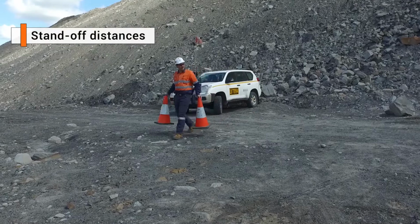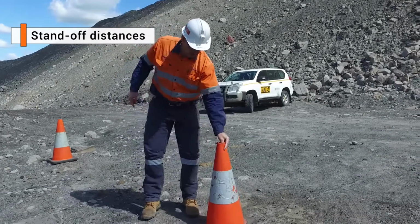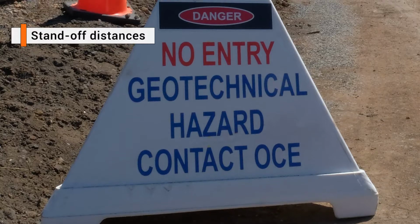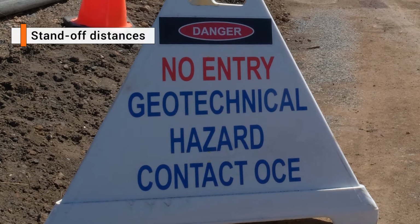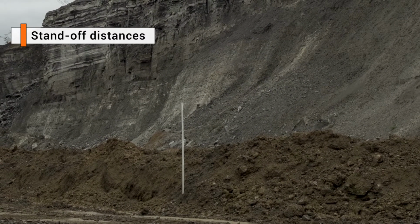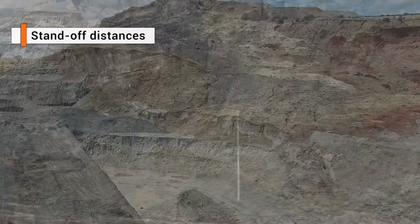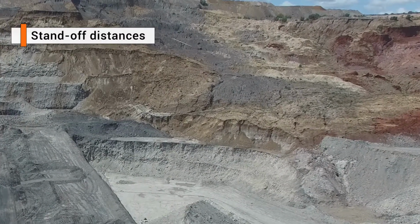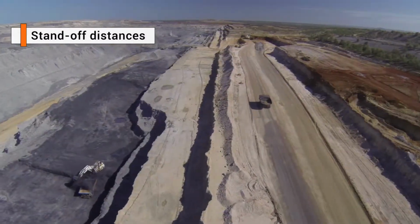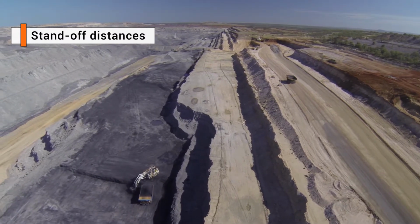Standoff distances can be applied at both the crests and toes of excavated or dumped slopes. Standoff zones are typically based on empirical charts, past performance of slopes with similar conditions, or modelling results from software simulating individual rockfalls or slope failures. The applied standoff distance should be appropriate for the type, size, likelihood and consequence of slope failure. Many sites have standard restriction zones that are applicable at all times. Increases or decreases to these standard restriction zones are then made on a case-by-case basis depending on the specific hazards present.